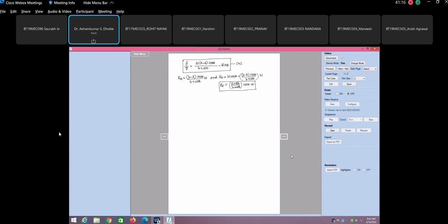Okay, now these are the front wheel reaction and the rear wheel reaction. So these equations are useful in calculating how much load has to be there, because your frictional force is dependent on this, because the braking force is equal to this particular reaction multiplied by mu. Since there is a weight transfer phenomenon, the Rr and Rf will not be equal.